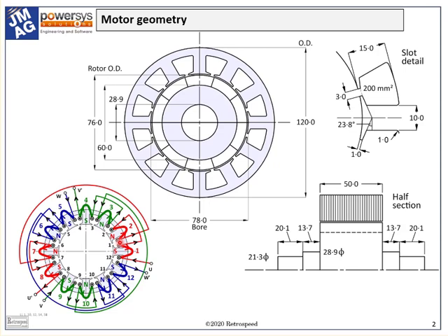There are 4 coils per phase, and in each phase we can find 2 groups of coils, each group comprising 2 adjacent coils wound with opposite polarity. The spacing between the axes of adjacent coils is 30 mechanical degrees or 150 electrical degrees, since the number of pole pairs is 5.